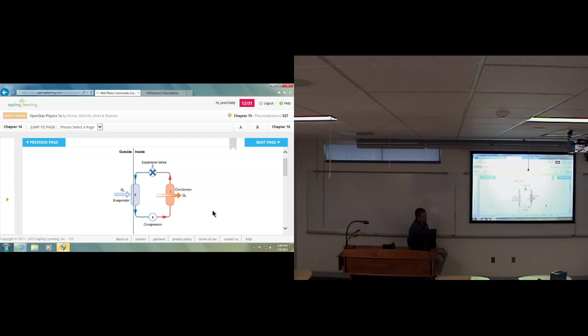You actually use what's called a condenser pump, and it's like forcing fluids to go backwards through a radiator. So you have gas that you force into a radiator backwards, it cools off the gas, turns it into a liquid, so it condenses it, and then you have that condensed liquid, and then you allow it to go into the hot part, which is the inside of the refrigerator, and then you allow it to evaporate. Well, that means it has to be a liquid that evaporates at a cold temperature. That is why we use Freon in refrigerators and inside